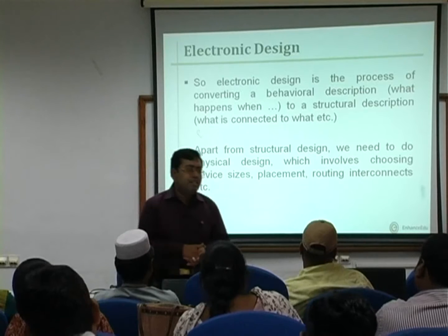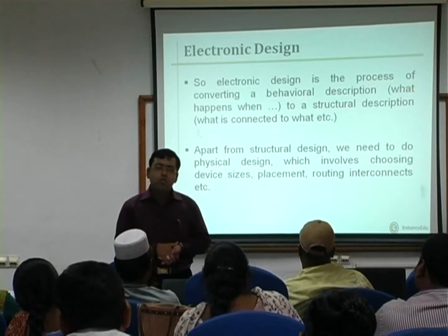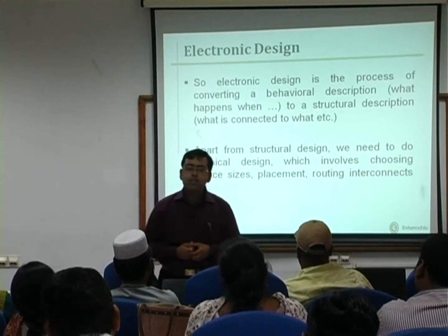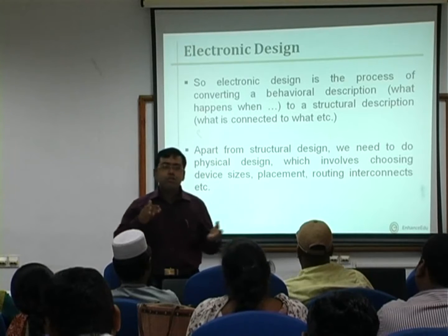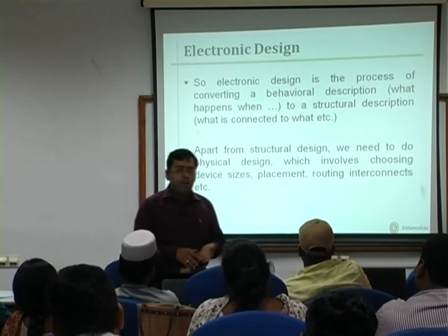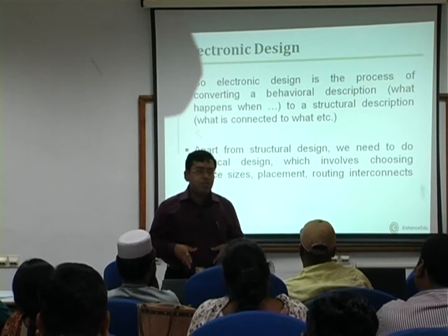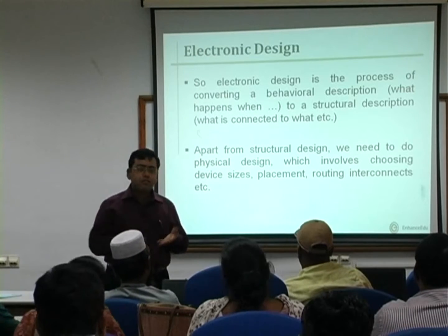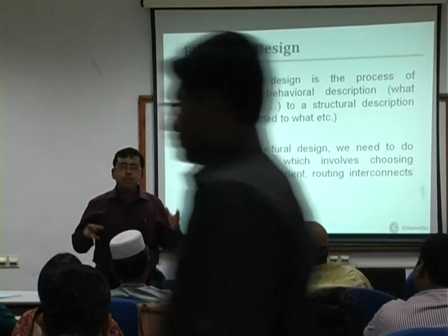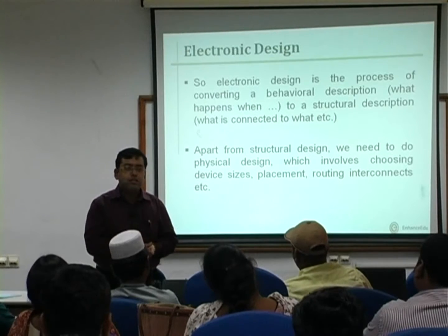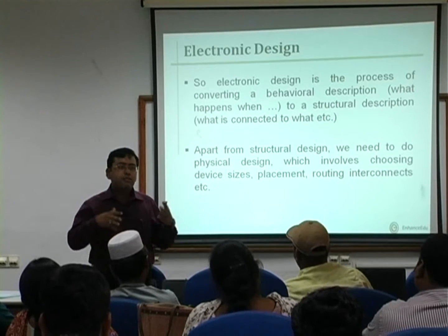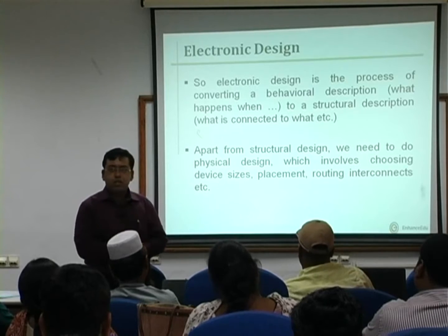Now when it comes to an integrated circuit, which means we talk of SSI, MSI, LSI, VLSI, ULSI, whatever level of integration it be, some more restrictions are put on developing the circuit. After ensuring what components we are going to build the circuit with, we translate the interconnection of components into geometric patterns that we transfer onto a silicon wafer during a typical lithographic process and develop the circuit on it.